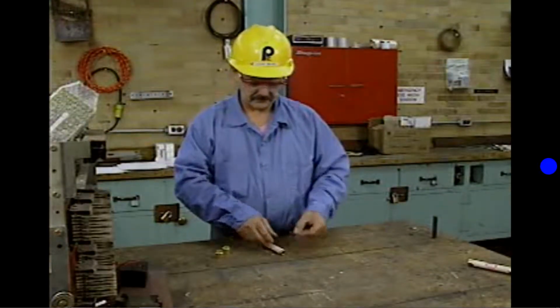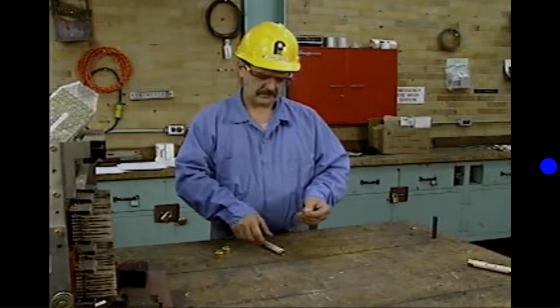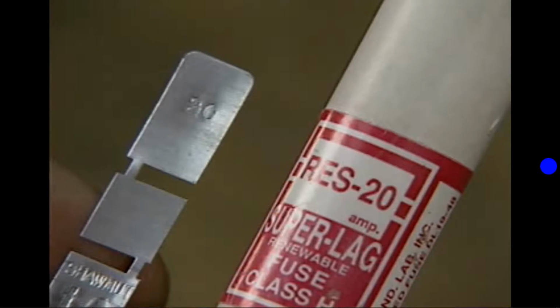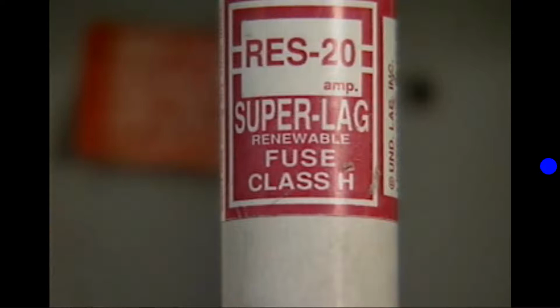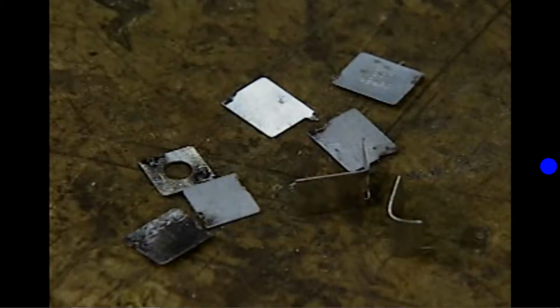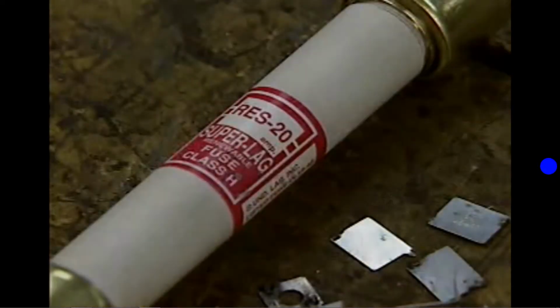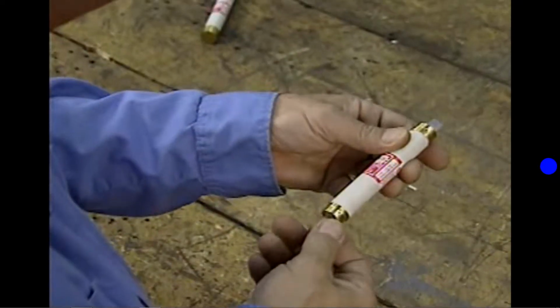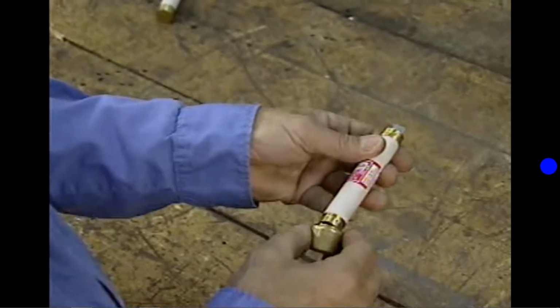Next, put in a replacement link that is the same type as the blown fuse link. Most renewable link cartridge fuses will accept links of different current ratings. You should make sure that you're using the proper replacement link by checking the current and voltage ratings stamped on the replacement links. Whenever you replace a fuse link, make sure that the fuse casing is labeled to identify the ratings of the new fuse link. This way, if the ratings marks on the link are destroyed when the fuse blows, the label on the casing will identify the proper ratings for the replacement link. After the new link is installed, screw the end of the fuse back on.